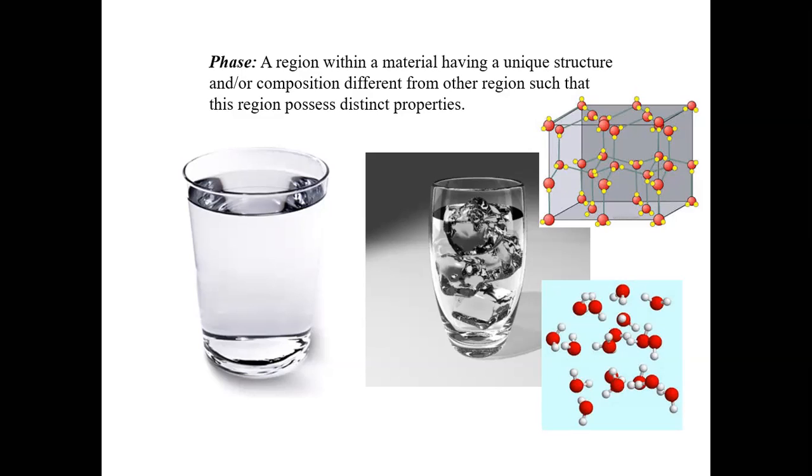So initially, suppose there's no solid at all. It's all liquid, and we think about the atomic picture. All the atoms are just randomly moving around and have this disordered nature. And then what happens after nucleation? Atoms get ordered within the liquid. So after the nucleation, you suddenly find a very tiny region in which all the molecules or atoms are magically packed in a very ordered way, like you find in a solid. Does this make sense?